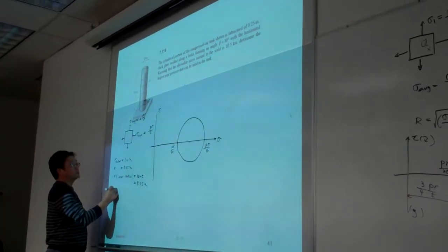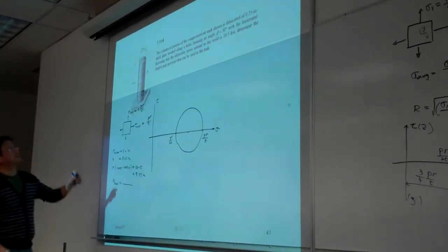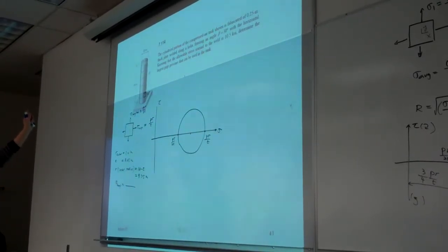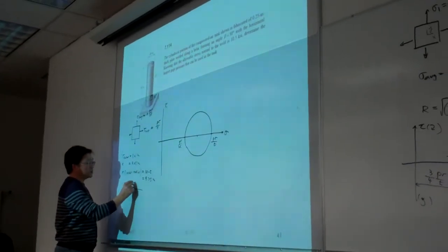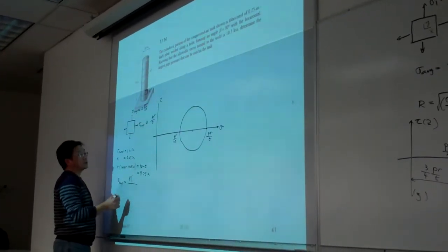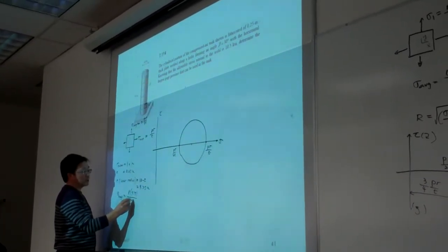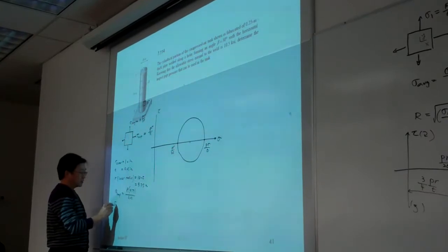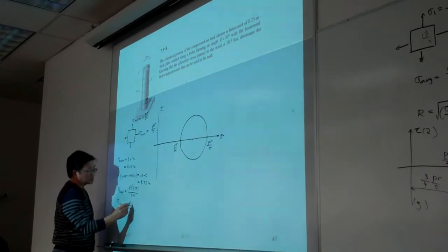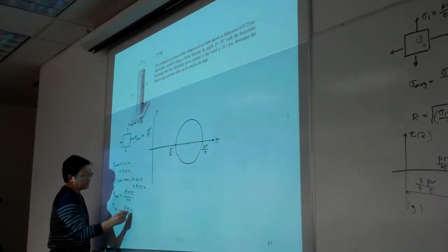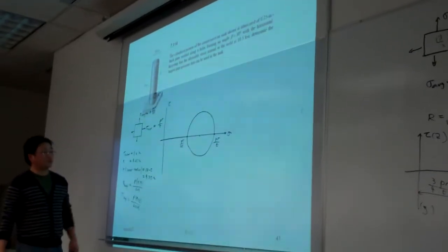Therefore, the hoop stress will be equal to PR over T. The P is how much? So here we want to determine the gauge pressure. So P is unknown, times R. R is 9.75, and T equals 0.25, and the longitudinal stress will be equal to P times 9.75 over 2T, 2 times 0.25. Okay, so here we have those things ready.